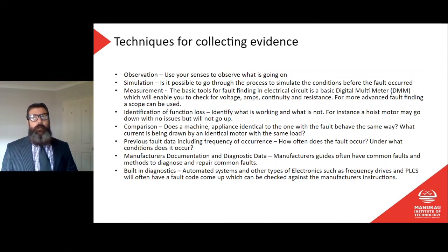That is something that I would do if it is an intermittent fault, or if it's a fault that only occurs under certain conditions. I want to try and simulate those conditions. If they say it only happens in the morning and I just cannot figure out what's going on, well, then my next step is, let's turn everything off and I'll go away and I'll come back in the morning and you guys do your normal thing and I'll see what happens. I'll watch you. So we simulate the conditions or observe the conditions directly.